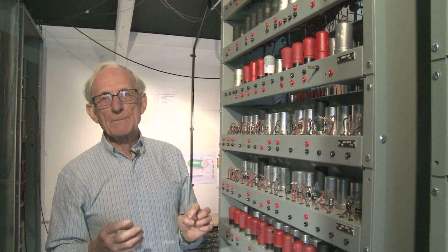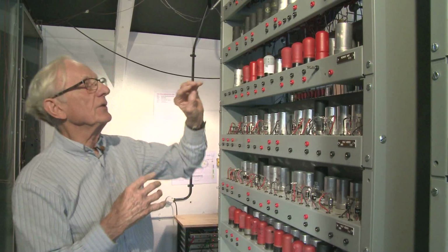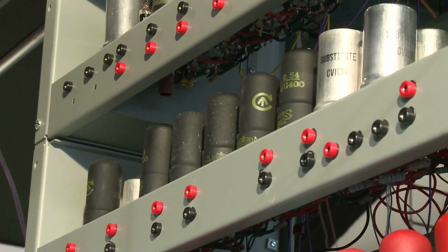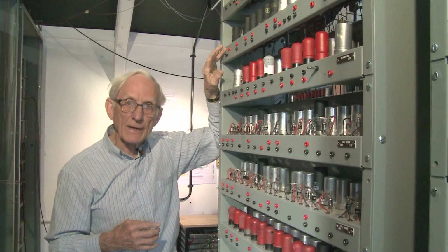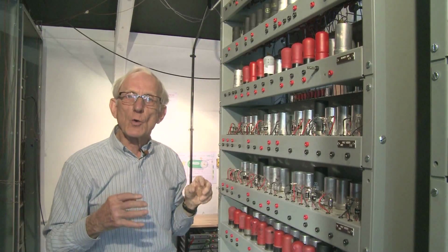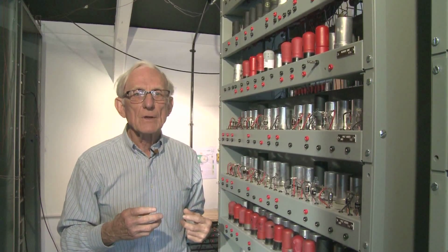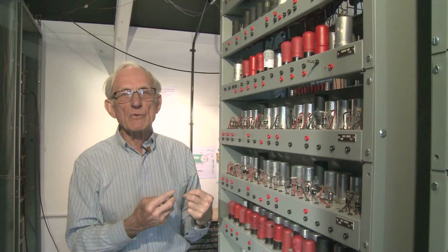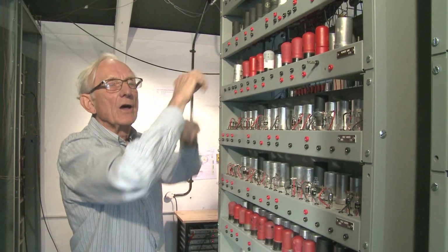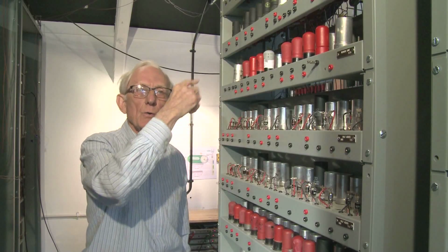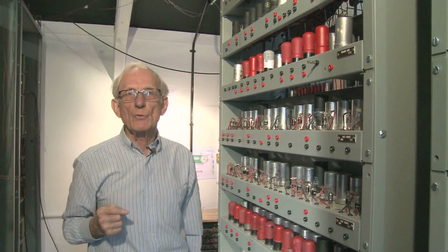we want to obey. And then lastly, there's one more tank here, which is just a plain register with no adder or anything, called the order tank. And that tank holds the currently being executed instruction. Once the instruction's got out of the memory, it's put into the order tank, and there it stays going round and round every half word, and so is available for any purpose that we may need.